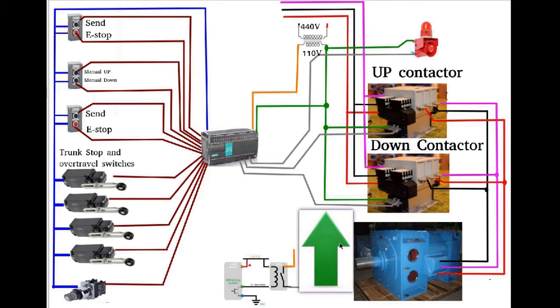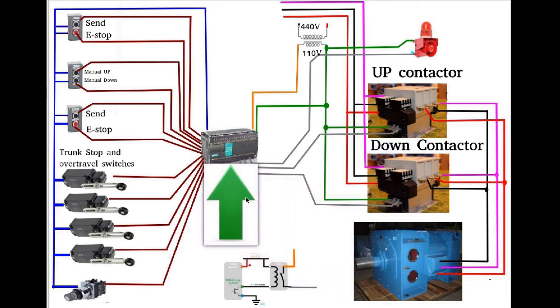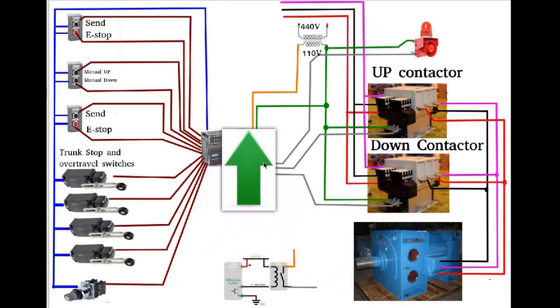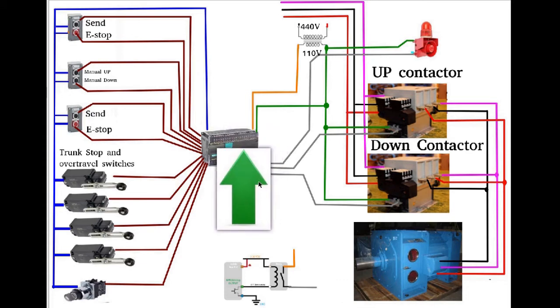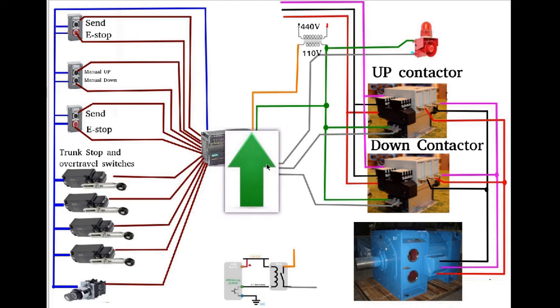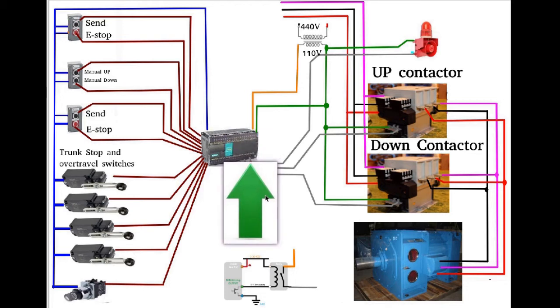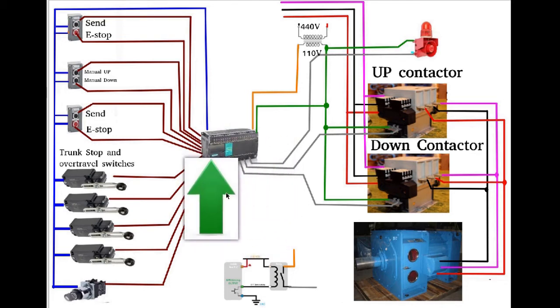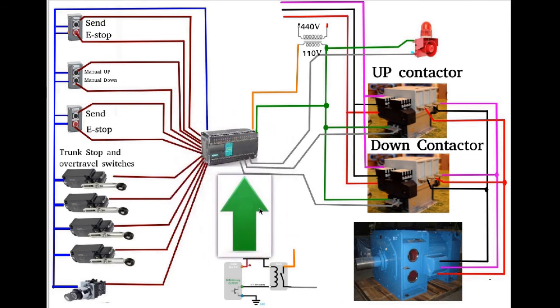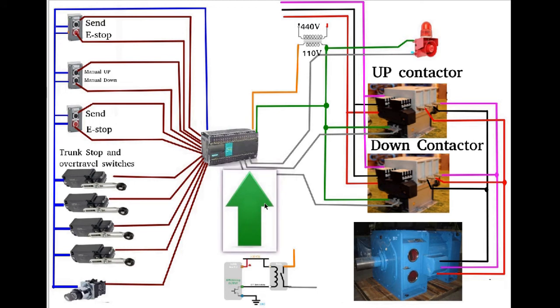The other leg of power is supposed to be supplied by the PLC. The PLC has 2 legs of power because that's how it comes on. It's 110, and it has its own internal power supply that converts it to the 5 volts and 24 volts required for different systems. Although this is a unit PLC, so it might only have 1 power supply for everything.